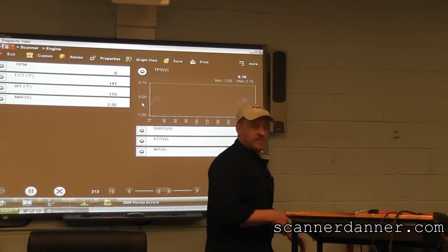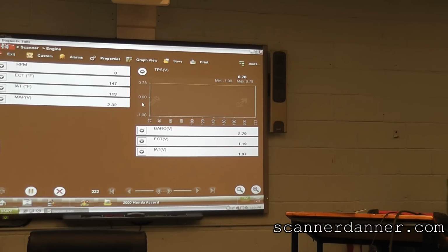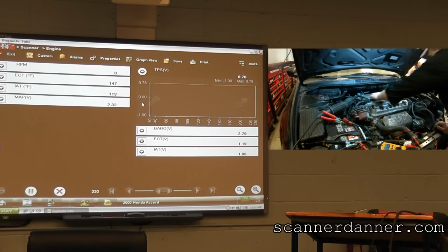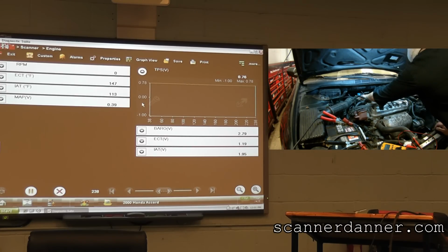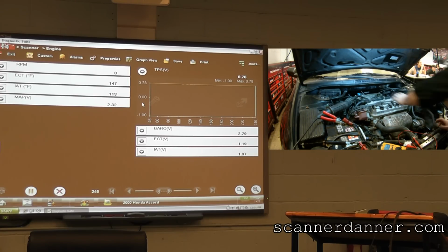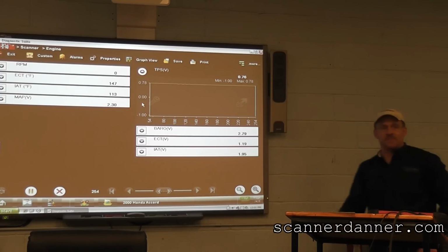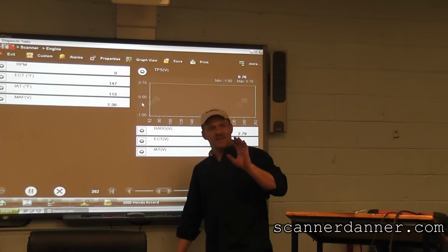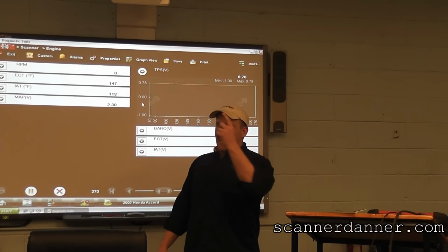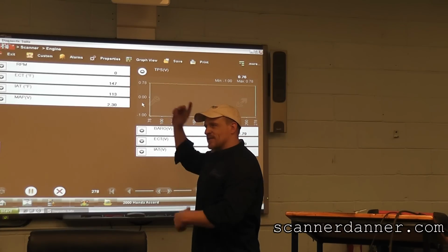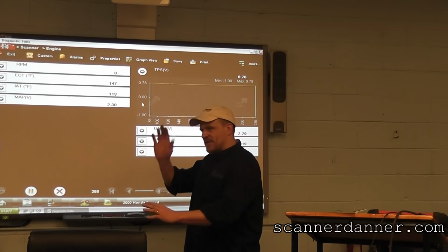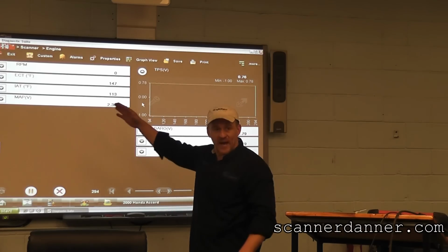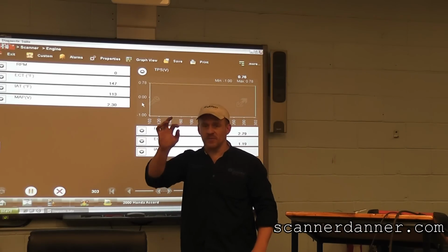So the next step for the TPS, we open and close the throttle, key is on, we look for a data PID change. There's wide open throttle, I let go, no change on the TPS. Red flag. Is that an actual signal? My next thought is, is that a substituted value? Can I rely on that? Different subject, but bad, right? Red X next to TPS.